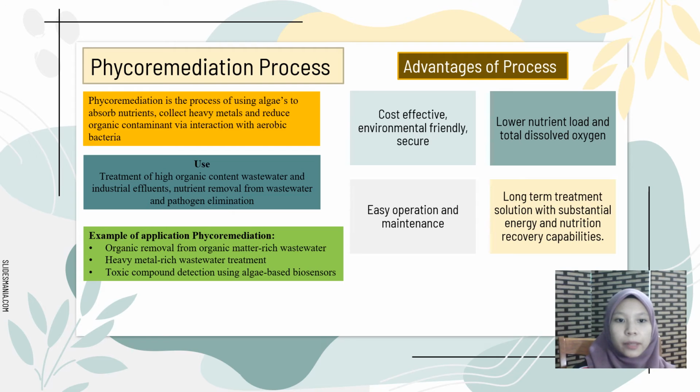Phycoremediation process. Phycoremediation is the process of using algae to absorb nutrients, collect heavy metals, and reduce organic contaminants via interaction of aerobic bacteria. They are used for treatment of high organic content wastewater and industrial effluents, nutrient removal from wastewater, and pathogen elimination. Examples of application of phycoremediation: organic removal from organic and metal-rich wastewater, heavy metal-rich wastewater treatment, and toxic compound detection